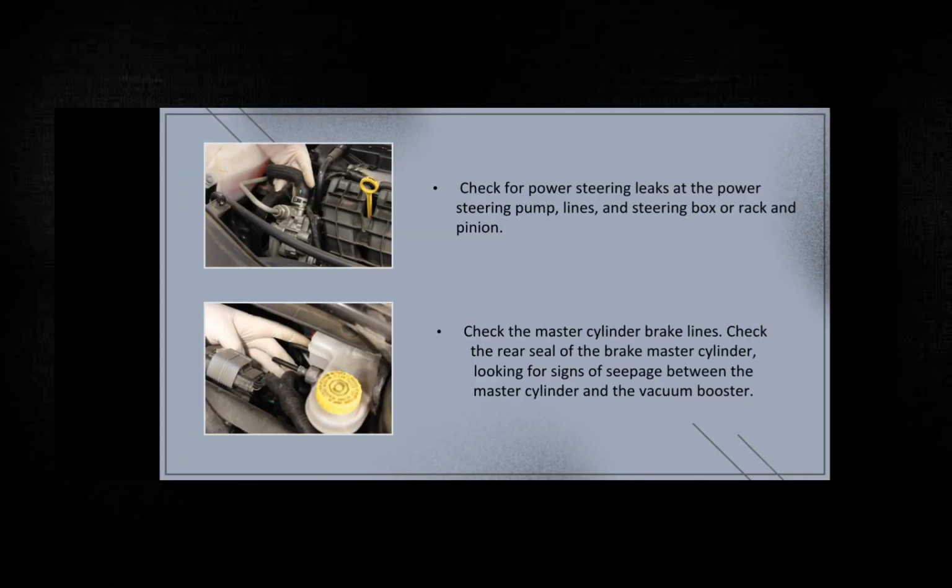Check for power steering leaks at the power steering pump, lines, and steering box or rack and pinion. Check the master cylinder brake lines. Check the rear seal of the brake master cylinder, looking for signs of seepage between the master cylinder and the vacuum booster.